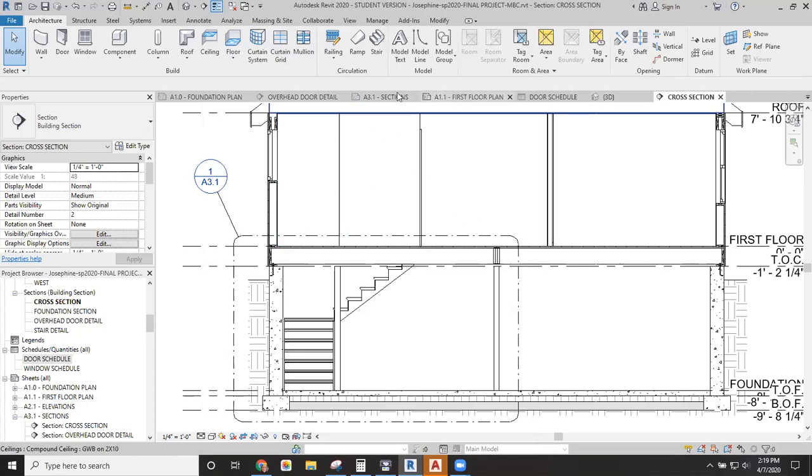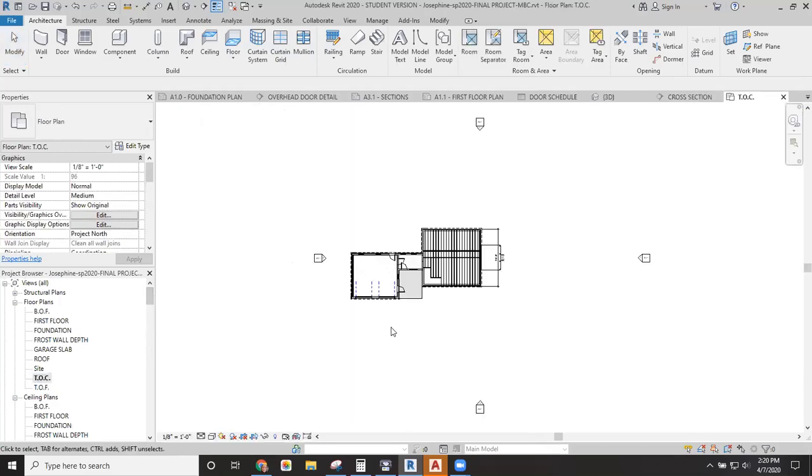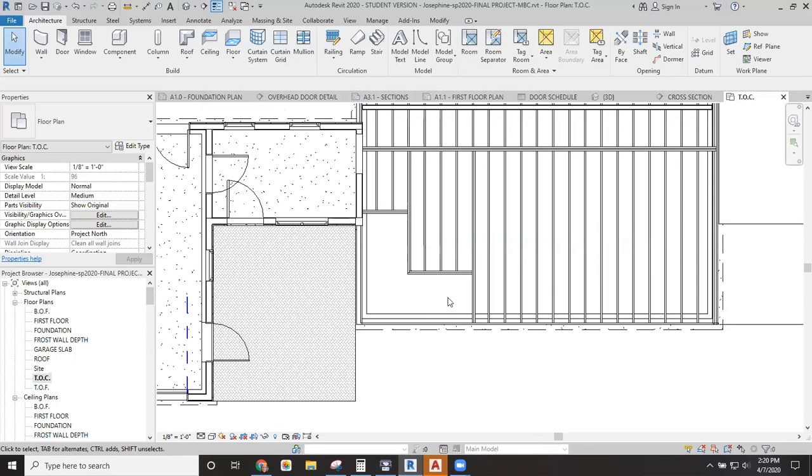And I just wanted to show you what this looks like in framing with the stair opening. I think I did this last class, but this is where those stairs would go. This is the opening for those stairs. That lally column is holding up the corner of the floor right here. We've got two floor joists doubled up together here and here to carry the weight for the header here and here. And you see how I did not have to have the top of my stairs attached to that middle header or middle beam. It's okay for me to move that over like that.